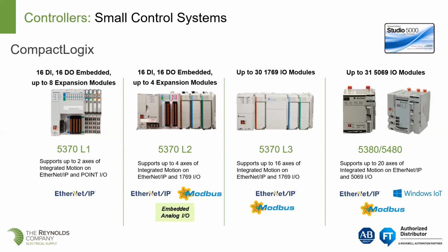Oh, Wayne, I was going to say, I use as a differentiator that the 5370 and everything below it is a dual core processor. The 5380 and the 5570 ControlLogix, those are all quad core processors. Learning where the demarcation line is is now kind of important.